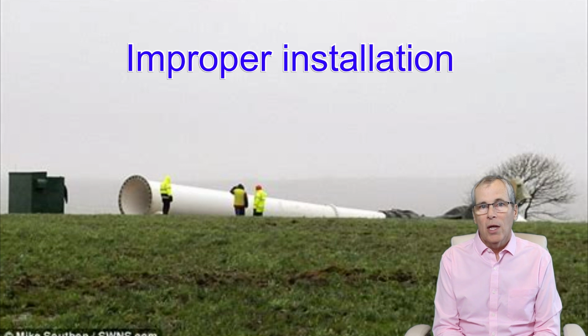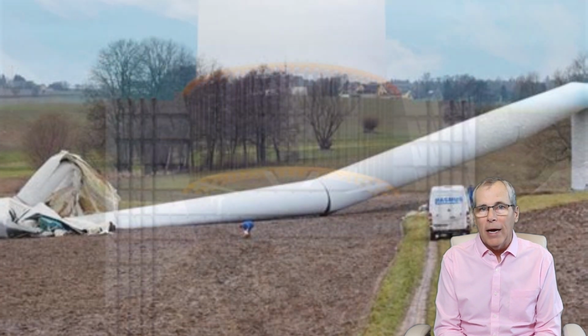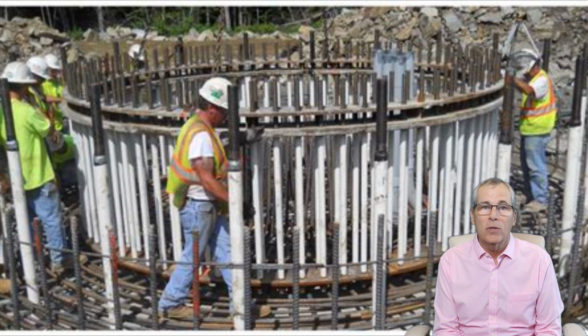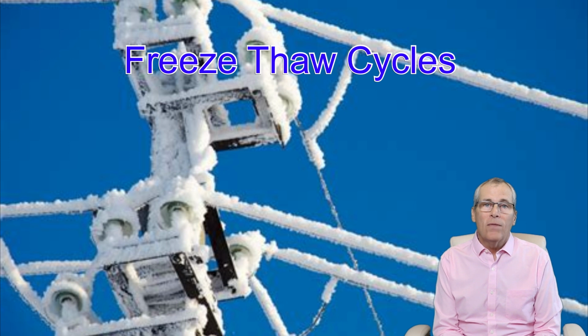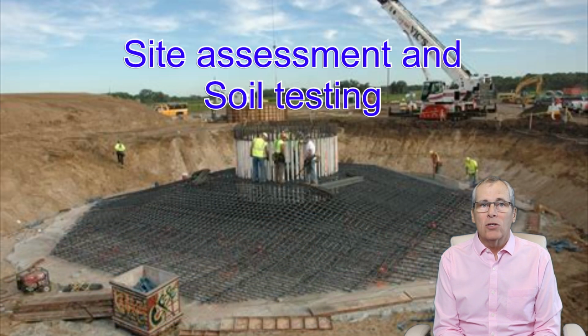Improper installation. If the foundation is not installed properly, it can lead to failure. For example, if the foundation is not deep enough or if the soil is not compacted correctly, it can lead to failure. Materials. Using the wrong materials for the foundation or using materials that are not designed to withstand the stresses of the environment can also lead to failure. Freeze-thaw cycles. If the foundation is not designed to handle the freeze-thaw cycles, it can lead to damage, and in extreme cases, failure. To minimize the risk associated with wind turbine foundations, it's important to have a proper site assessment and soil testing before the foundation is designed or installed.